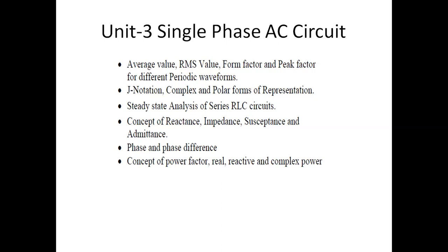After that, you have to know about the phasor and what the phase differences are. Suppose you have some voltage and current, and you look at the phase of that quantity. Suppose you have a sine omega t, then omega t represents the phase of that quantity. Just suppose there is another quantity represented by a sine omega t plus phi. The first quantity has the phase omega t, and the second quantity has the phase omega t plus phi.